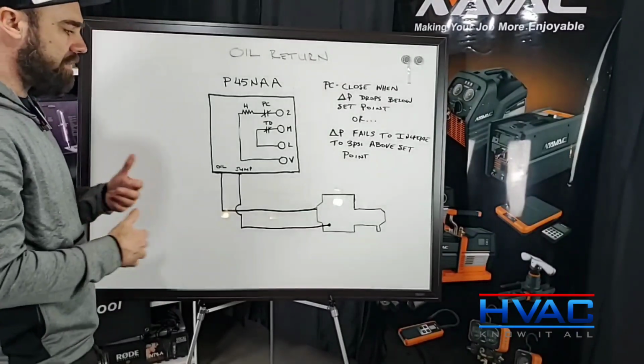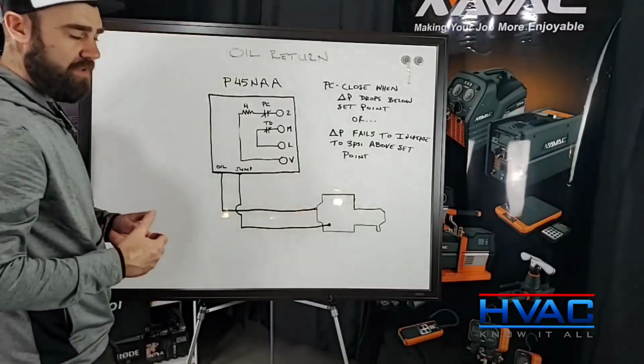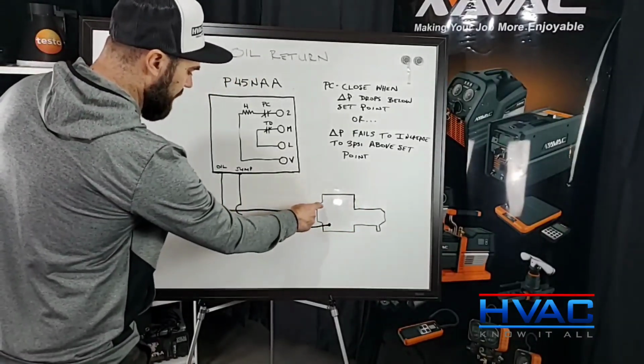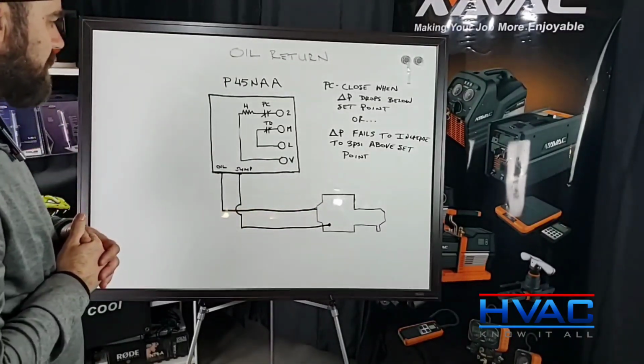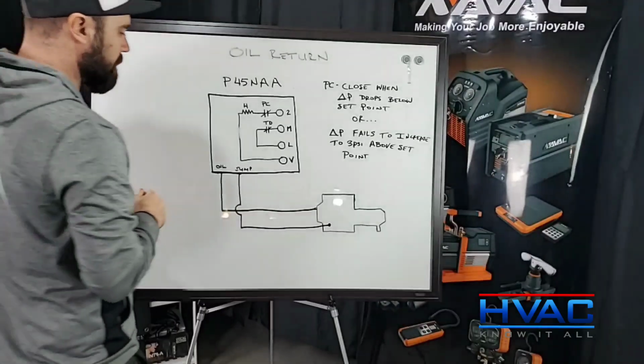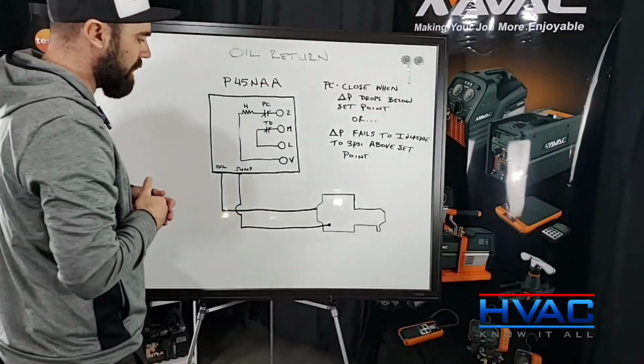So when the compressor starts up, this oil is going to be drawn into the pump, moved across the crankshaft, but we're teeing off to get the pressure here. So we want 5 psi differential. All right, while that 5 psi is building, our compressor is going to run.